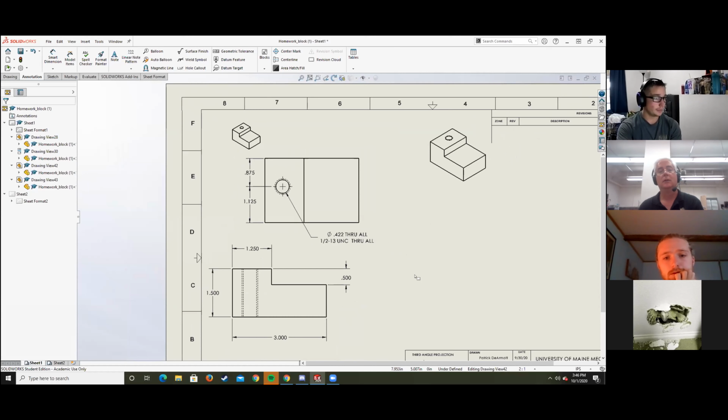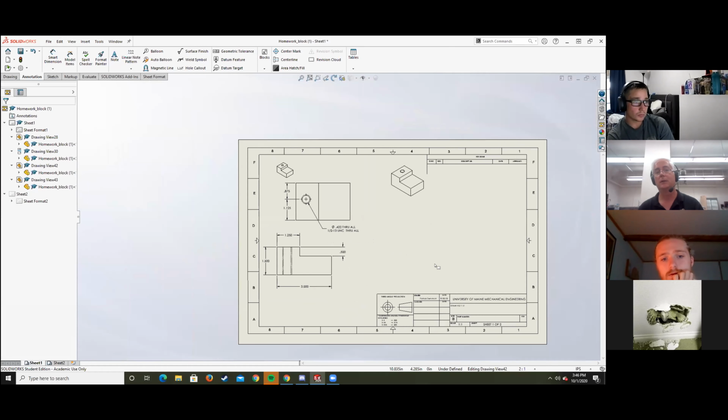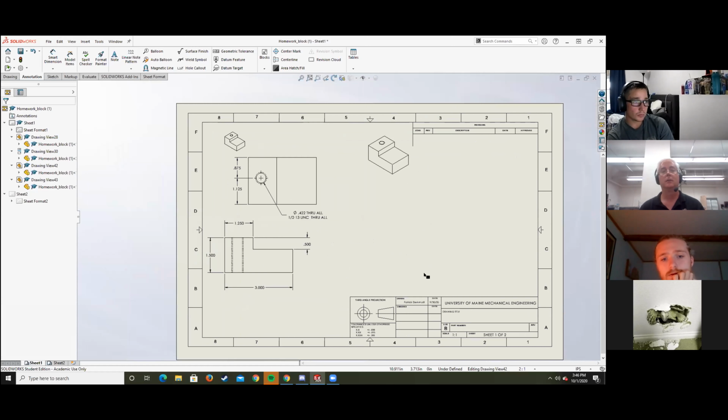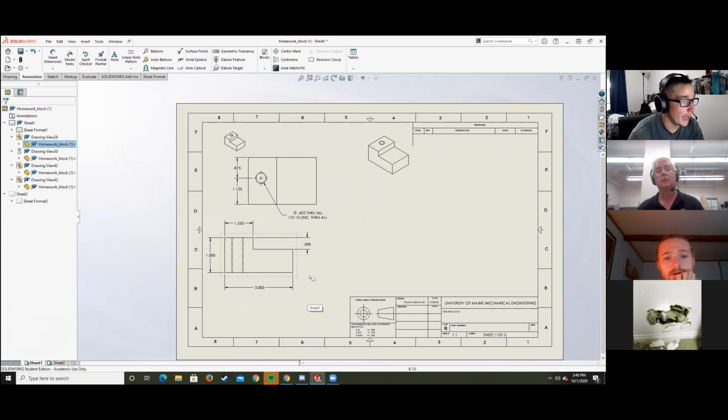Yep. Okay, so the other thing that I would ding you on right now, besides having two isometric views, which wasn't what caught my eye: your views do not line up vertically. Think about the glass box. The rightmost edges in that view should line up with each other. Okay, yeah, I hadn't messed with that quite yet.